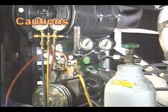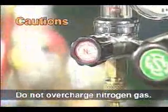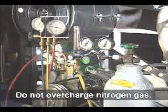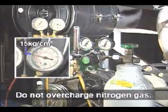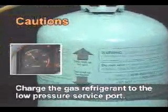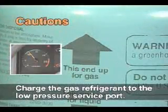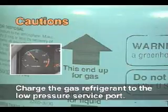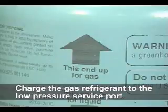When you service the air conditioning system, pay attention to the following things. Do not charge the nitrogen gas more than 15 kilograms per square centimeter when nitrogen is used for the leakage test. There is a risk of explosion when overcharged. When charging refrigerant, maintain 1,100 RPMs and charge the gas state refrigerant through the low pressure side port. If the refrigerant charging method is wrong, serious compressor malfunction can result.